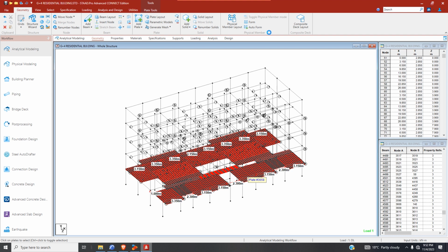So I will select the entire structure, then come to geometry because there are multiple structures and then intersect beams. Okay, and then check again structure, multiple structures. So I go to node, remove open nodes, and structure. Okay, close.